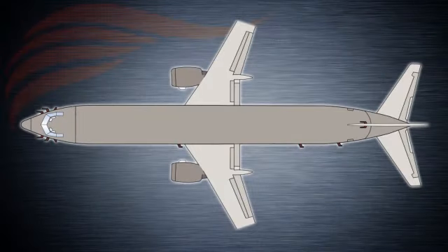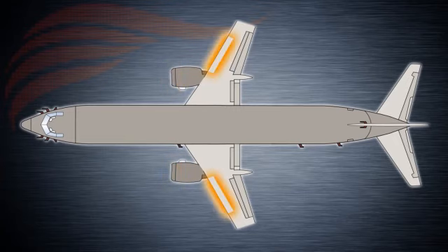The Next Generation 737 has ice protection systems for the engine inlet cowls, the wing leading edges, the air data probes, and the flight deck windows. Water and waste system lines and drains are also heated to prevent ice expansion damage and blockage. Drain masts on the underside of the fuselage are heated to prevent ice formations from breaking off and damaging the aircraft structure. The aircraft also has windshield wipers and a rain repellent coating on the flight deck number 1 windows for rain removal. Conditioned air from the left pack can be routed to the number 1 windows for defogging as well.